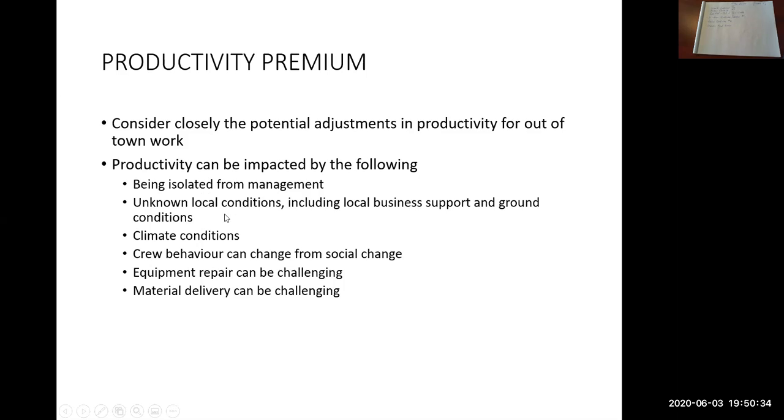Next one here, unknown local conditions, including things like business support and ground conditions. Are the ground conditions significantly different than what you're used to? Is it harder? Is it more dense? Is there way more rock? Is the groundwater, you know, much higher than what you're used to?